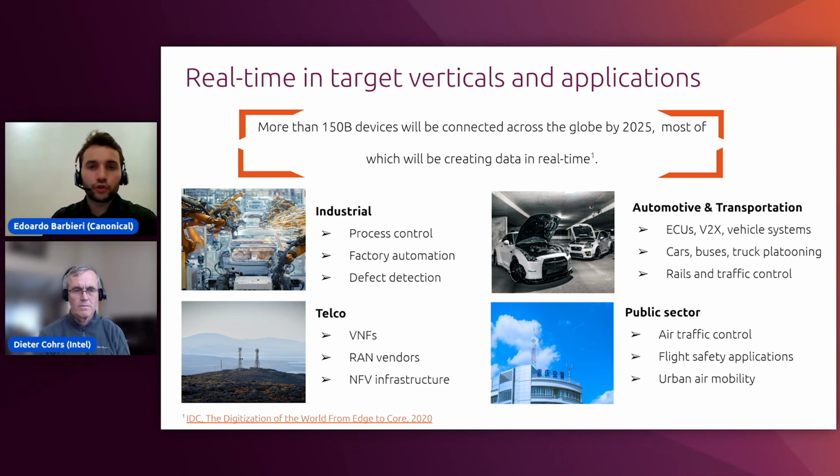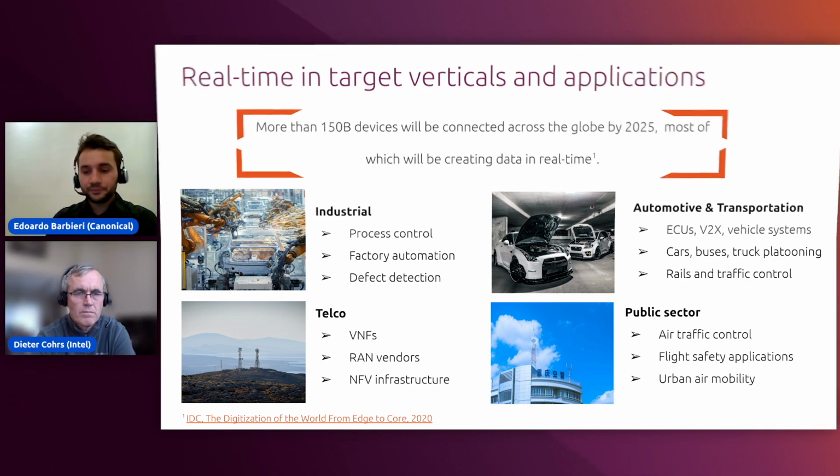For instance, a motion control for a robot will not require the same performance that a conveyor belt would require, and a CNC machinery with precision drilling, they would have very tight control loops. So it really depends on the function. You can see very low control cycles in PLCs with tight requirements, and the latency being stretched to microseconds. But we can also see those requirements being more relaxed and less stringent when looking at the synchronization between robots on a conveyor belt, for instance.